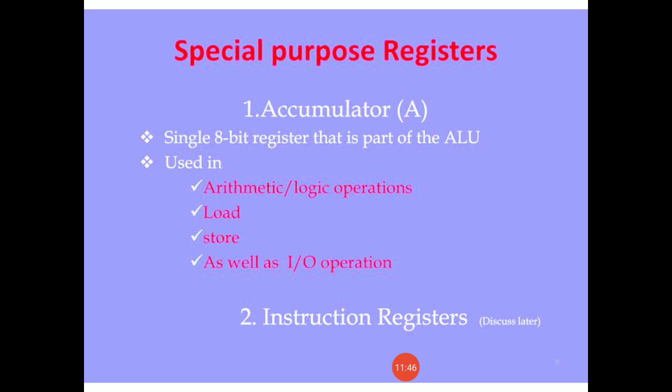The next classification is special purpose register, and under special purpose register first we'll study the accumulator. If you say accumulator or register A, both mean the same thing. The accumulator is an 8-bit register. 8-bit means it will store 8-bit data only. So it is an 8-bit register associated with the ALU, that is arithmetic and logic unit. It is used to hold one of the operands of an arithmetic or logical operation.